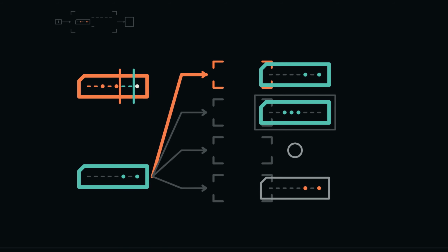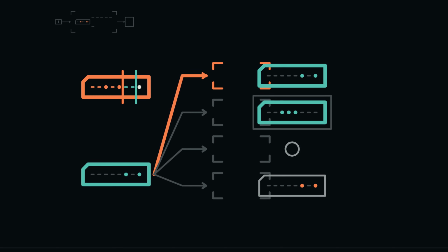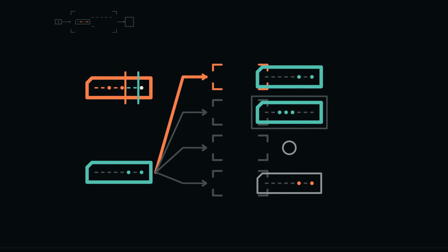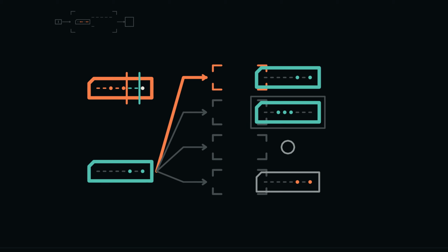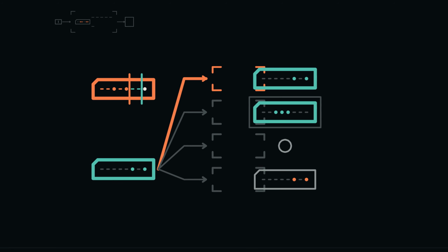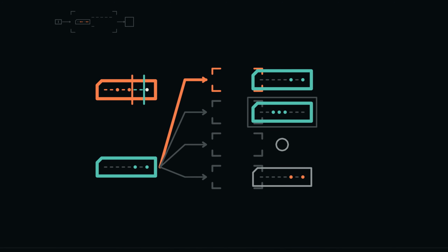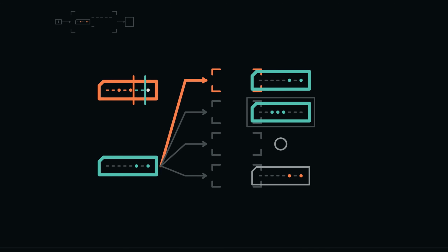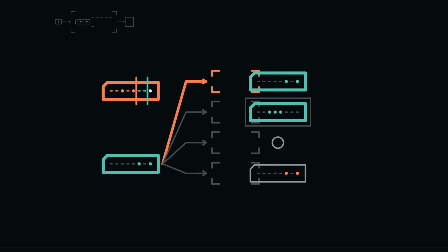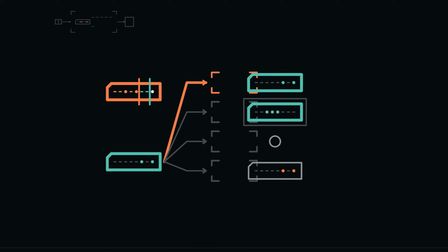Decode a new pair before the labels settle. Hexadecimal 29 followed by 05. The upper 5 bits of 29 select opcode 5, add. Field A is 00, selecting R0. I is 1, so B is immediate. Byte 1 supplies 5. The instruction is add immediate to R0, 05: add 5 to the current R0, and write the low 8 bits back to R0, updating all 4 arithmetic flags. If I had been 0, B would need to name a register in its low 2 bits instead. One mode bit changes the operand source, not the addition rule.